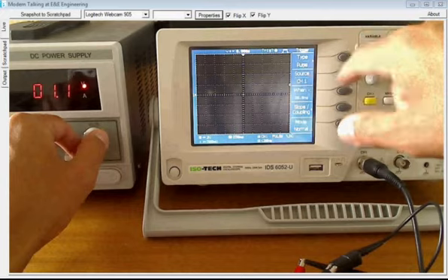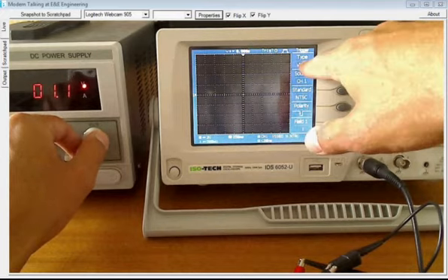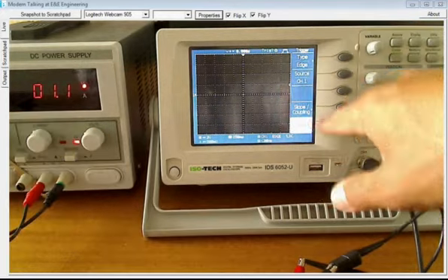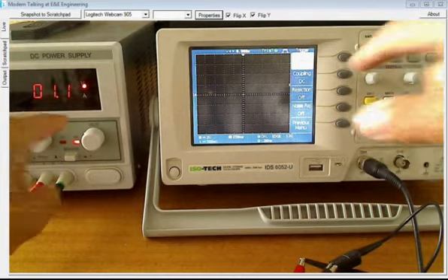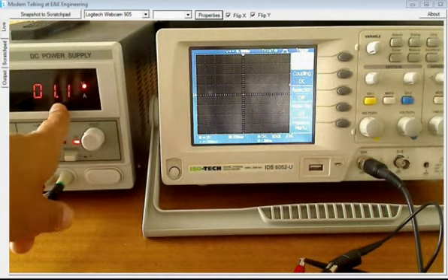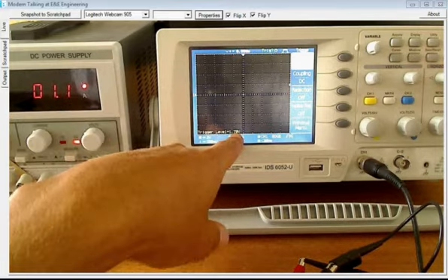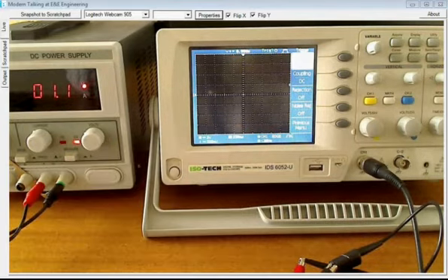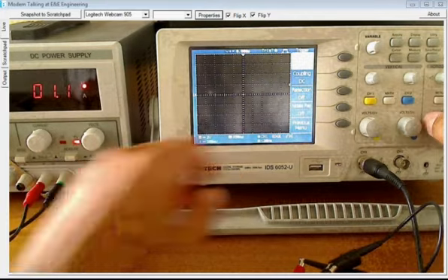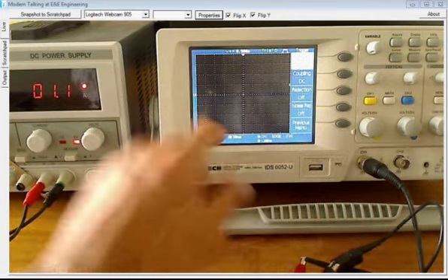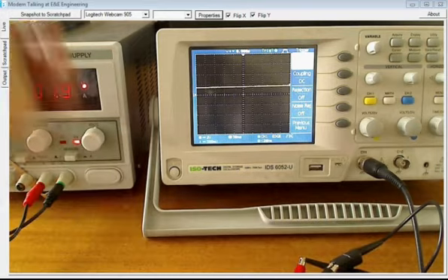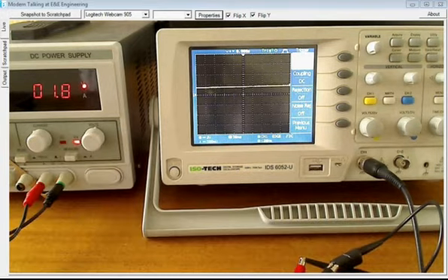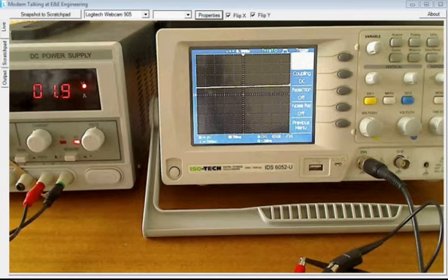I'm triggering on a rising edge. So I'm going to go from 1.1 to 1.7, and at 1.7 I'm expecting this to trigger. I'm just going to make it a bit faster, so I'm putting this on 50 milliseconds. So as I go through 1.7 now, it triggers. There we go, it shows me the signal. Okay, and I think that's more or less all you need to know.